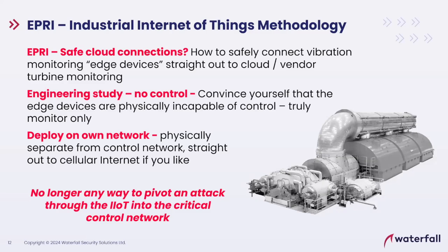You do an engineering study on the edge devices, on the devices that are physically measuring the vibration. Prove to yourself that they are measure only, that they cannot control anything. Not that there's a software switch that they might control stuff or not. No, they're not physically able to control anything.